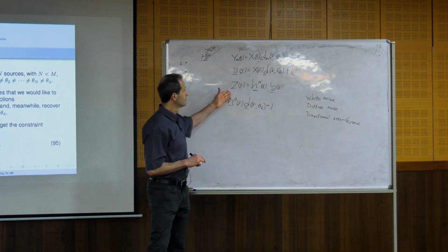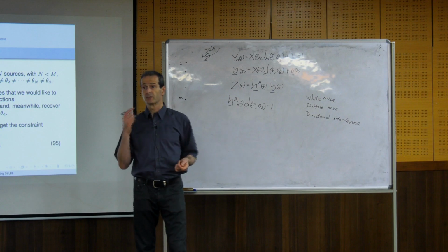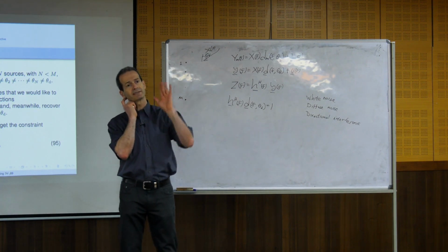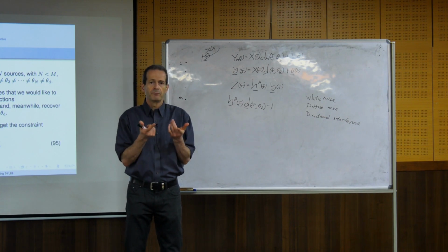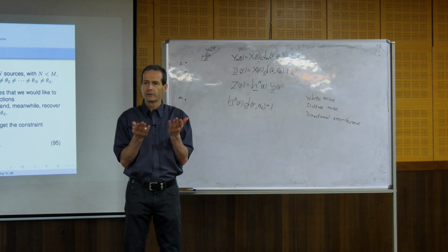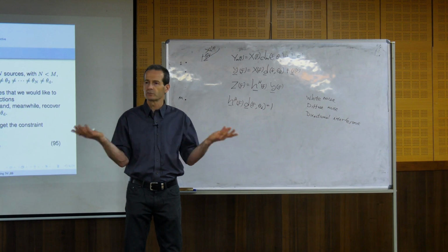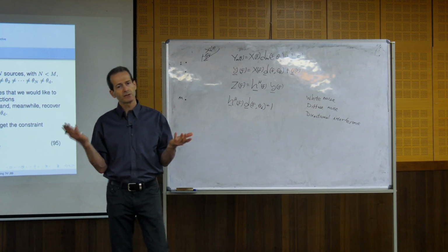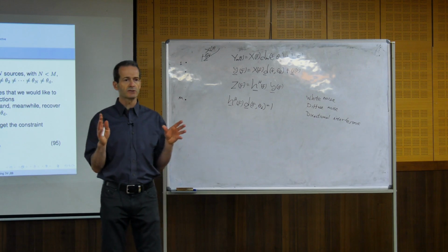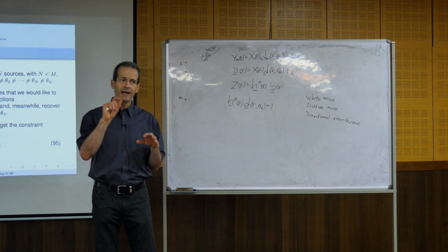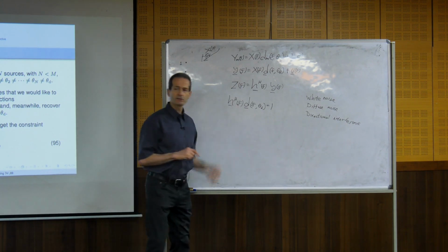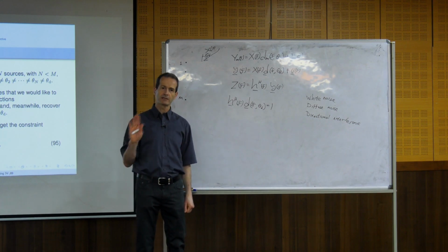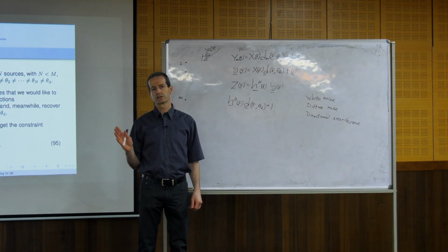With beamforming, we don't know the statistics of the signal. We don't know anything about the signal. We just know that it comes from a certain direction. So we cannot compromise between signal-to-noise ratio or noise reduction and signal distortion because we don't know what the signal is. So we cannot use a constraint that will allow some distortion of the signal. So we use this constraint, that the signal that comes from that direction will have no distortion at all.